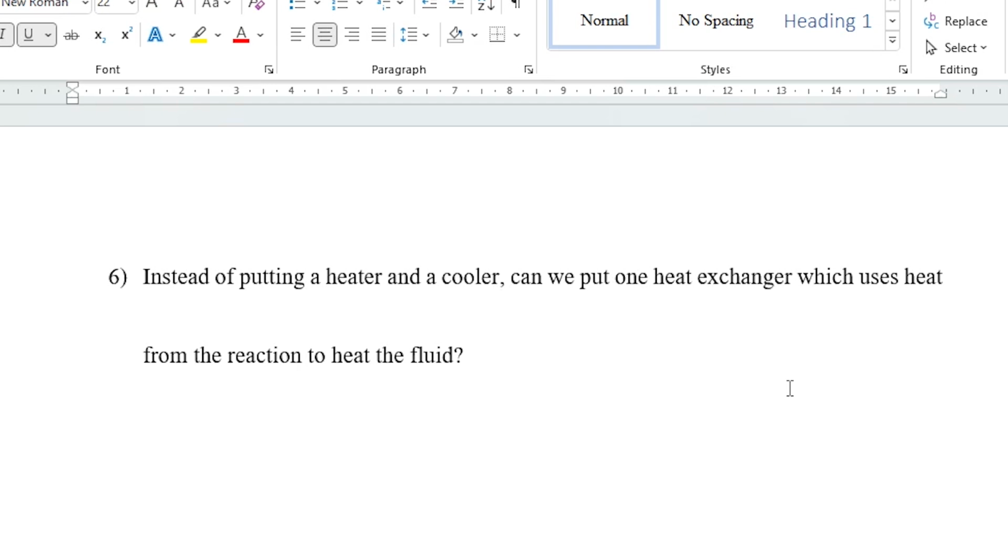So yes, for example in the dehydrogenation reactor, where you are injecting the feed, feed preheating is required. So you can preheat this feed by the product from this reactor. So these possibilities are possible in case of different processes.